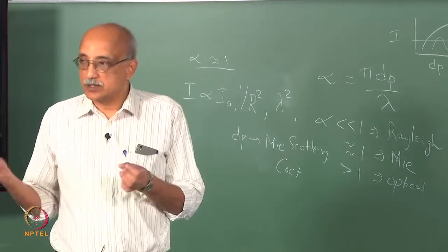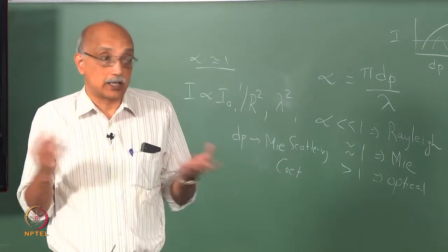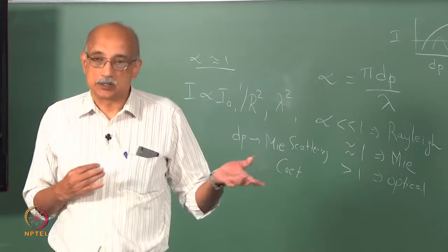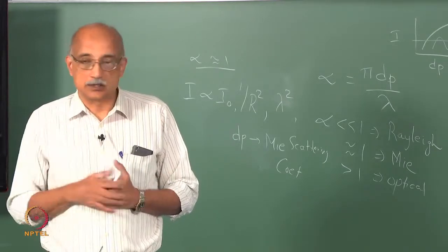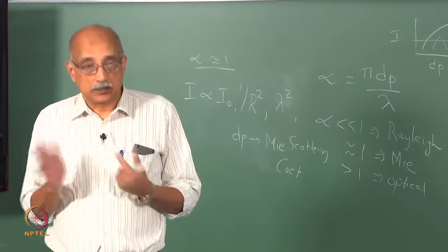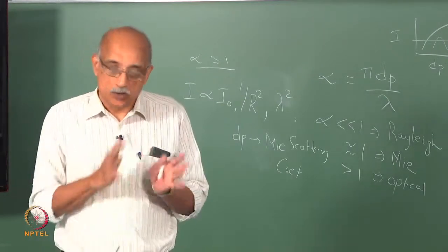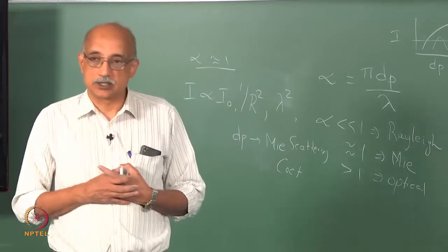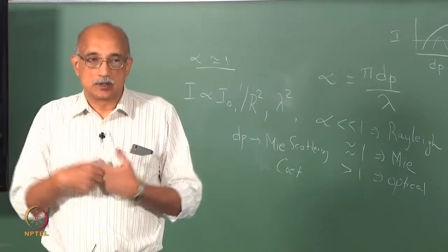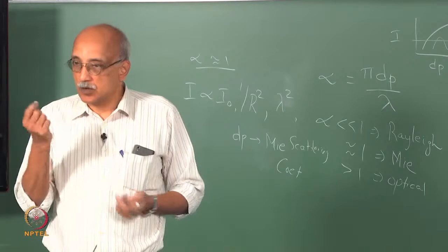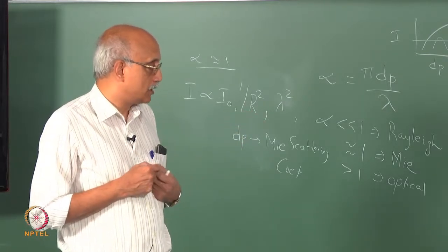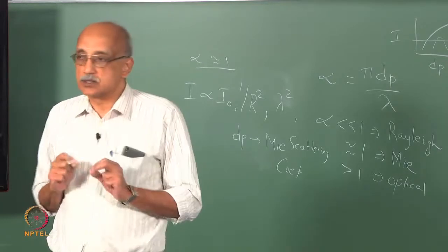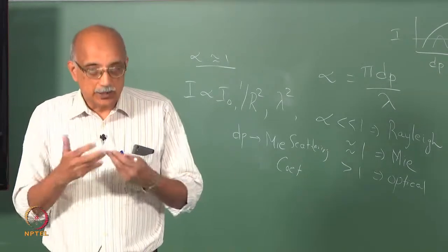The amount of vapors that are emitted may be very, very small, but it is happening, particularly with polymers. Any plastic material will outgas small quantities all the time. Metals less, but certainly non-metals will outgas to a significant extent. So these vapors can recondense and form small nuclei. That is the mechanism of formation of the finest particles in an indoor environment, which can then again agglomerate,